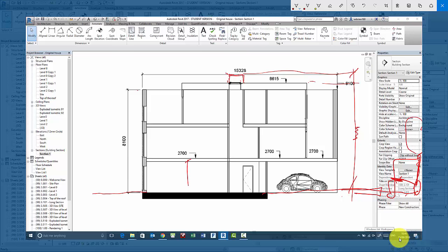The internal dimensions are important, because if you're dealing with estate agents, they always say things like, oh, is there high ceilings? Is there low ceilings? So if you have even a ceiling that's 300 millimeters higher than the average, and the client agrees to it, it adds quite a lot to the price actually, because it's just more pleasant to live in a house like that. The minimum in Denmark is 2.4. In other countries, it's 2.45. If you have it up to 2.7 or whatever, you're talking about a high quality development. Here I can see it's 2.7 floor to floor, so this is probably 2.45, 2.5, something like that inside.